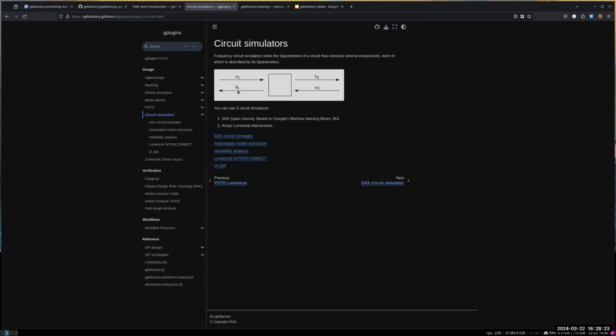So for example, if I want to compute B1, I can get the S. It will basically come from the multiplication of the input field by the reflection. So if you have a reflection of 10% and then you put one here, you will get basically a 10% reflection. You can also measure transmission, which is basically S21 or S12. Most of them are reciprocal devices.